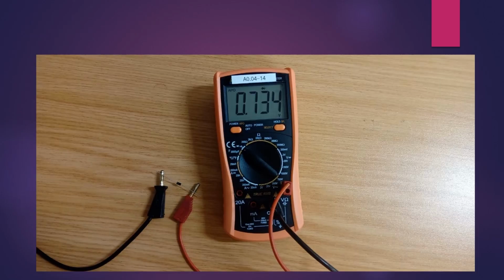So on this slide, I'm showing you how to measure a diode. As I've said on the previous slide, everything is there. You put your dial selector on your continuity scale and you press hold. Once you press hold, it's going to show you a diode sign, as you can see there on top. Then your red lead is on volt ohm, your black lead is on common.